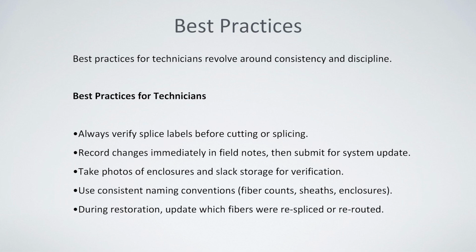Best practices for technicians revolve around consistency and discipline. Technicians should always verify splice labels before cutting or working inside an enclosure. Any changes made in the field should be recorded immediately, first in field notes and then submitted to ensure the official documentation system is updated.